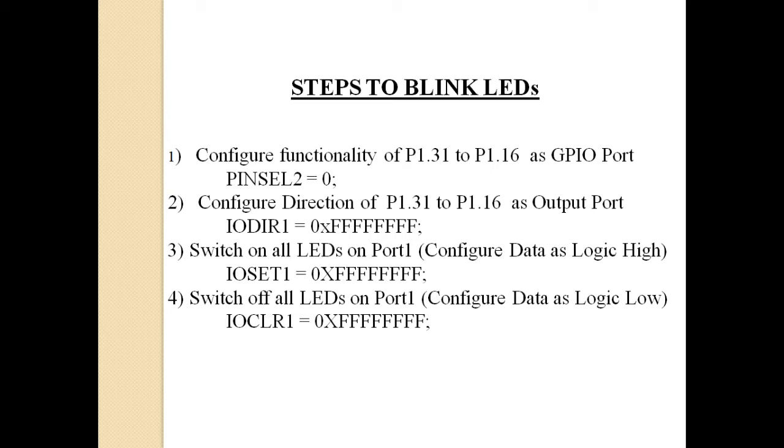First step is you need to configure the functionality of those pins as GPIO port pin. Second step is you need to configure the direction of those pins as output port pin or output direction, because you are connecting an output. LED is an output device, you are connecting that.